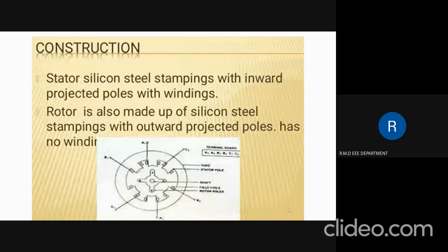Now, by sequentially switching currents in the stator windings, the rotor is rotated. The movement of the rotor, hence the production of the torque and the power, involves switching of current into the stator windings, and there is a variation of reluctance. Therefore, this is a variable speed motor drive and is referred to as switch reluctance motor. It is a direct derivative of the single stack variable reluctance stepper motor, in which the current pulses are phased relative to the rotor position in the continuous rotation mode.